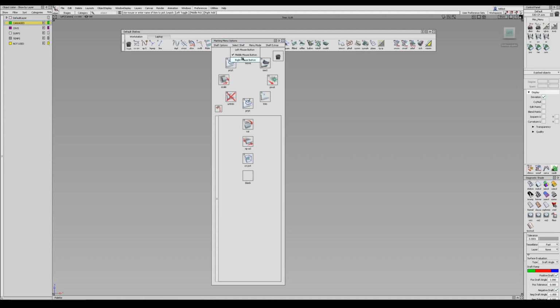And then if I go to the right mouse button for my marking menus, selecting those templates, controls on, control off, hide unselected, visible, so those kind of go hand in hand. Hardware shading, I'm a huge hardware shade fan, and then I'm always toggling the model in order to see the hardware shade. And then this guy right in the middle, query edit. This tool is amazing. You have to use this. It allows you to access the construction history of geometry, get a lot of information from some geometry, and just in general, I'm always using query edit.